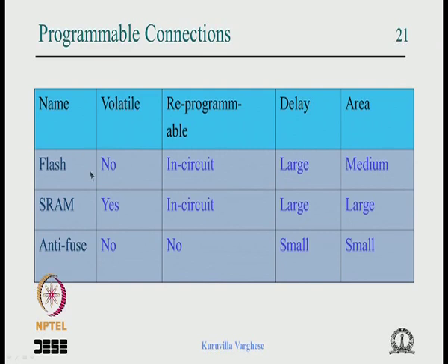It's not that when you design with an FPGA you program it 1000 times a day, because it takes time to design, and the designers do a lot of simulation and verify everything before going to the chip to program it. But still SRAM has no such great limitation on the number of times it can be programmed.